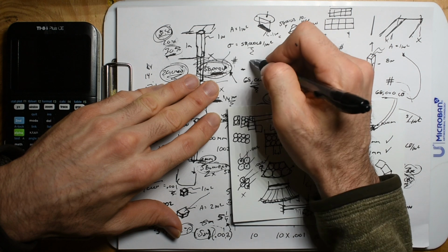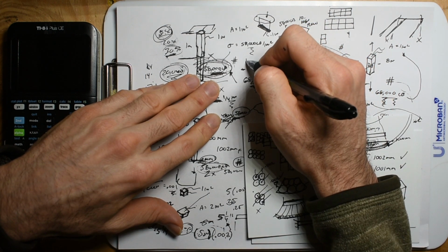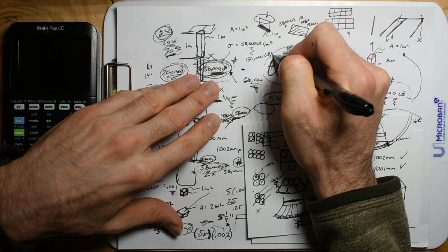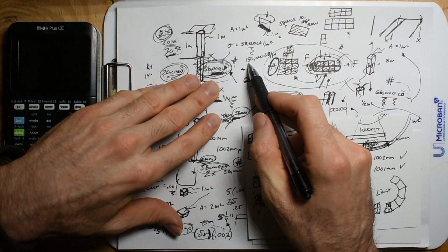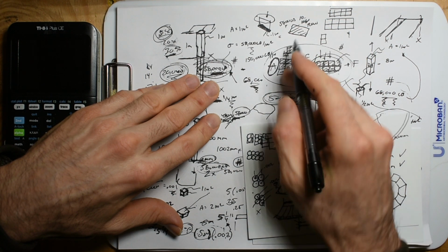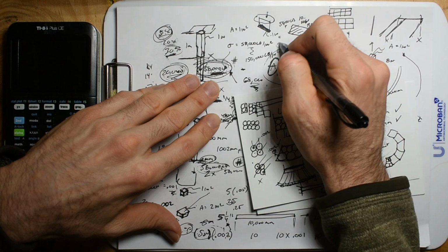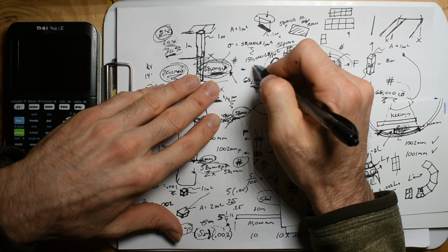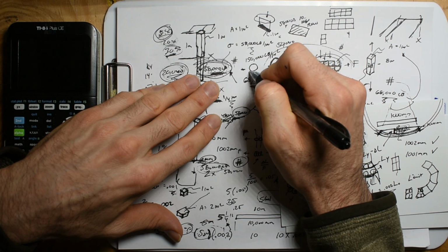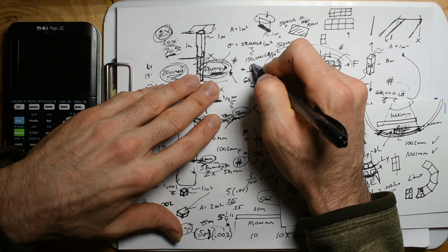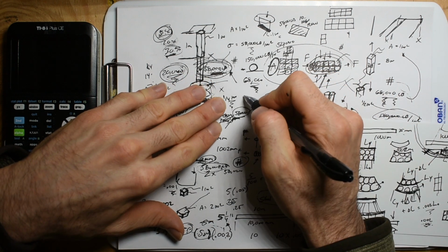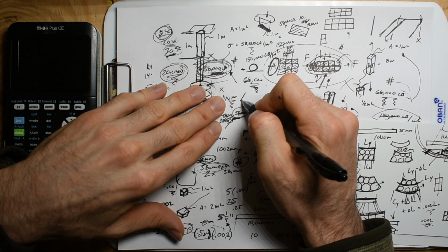And so that's what happens with train tires, and that kind of rounds it out, because I talked about train steel, its strength is 150,000 pounds per square inch, 3 times the conventional 50,000 pounds. And what happens with the train tire is they weigh a lot, and there's enough wheels to do the job, but you still have a contact patch.